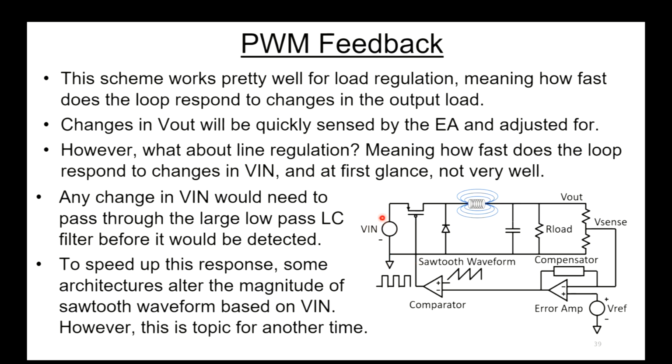To speed up this response, there is another architecture that alters the magnitude of the sawtooth waveform based on V in. So as you change V in, you can alter the magnitude of the sawtooth waveform, and that can affect the pulse width modulated signal almost instantaneously. I think that's called voltage mode feed forward.